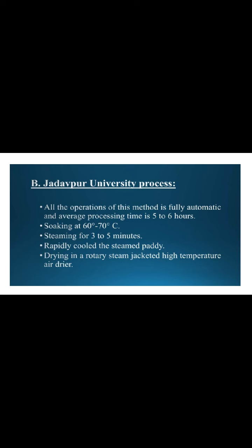Then the Jadavpur University process. All the operations of this method are fully automatic. The average processing time is 5 to 6 hours. Soaking is done at a temperature of 60 to 70 degrees Celsius. Steaming time is 3 to 5 minutes only. Then rapidly cool the steamed paddy, and drying is done in a rotary steam jacket high temperature dryer. This is the Jadavpur University process.